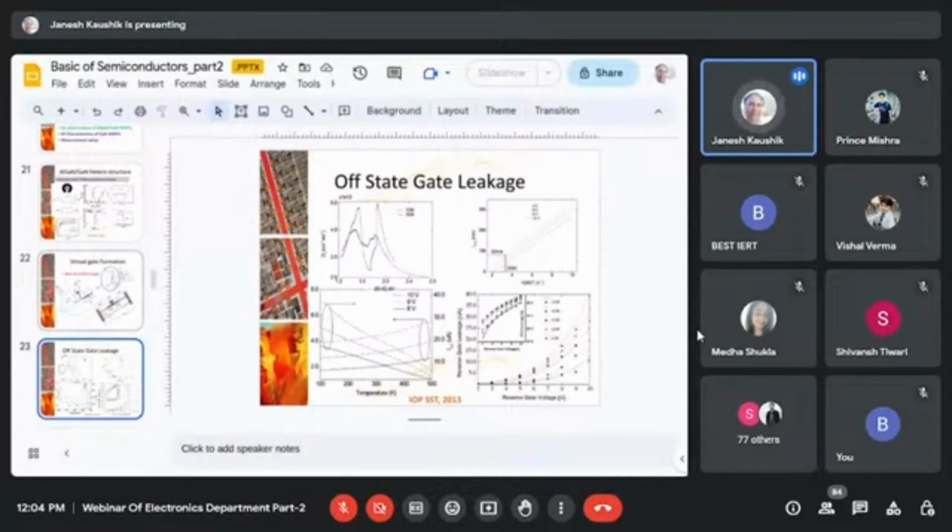The moment we get the D_it, we can integrate to match with the 2DEG available in the channel to calculate where our Fermi level lies. The moment we calculate where our Fermi level is, we can calculate how many carriers are available and how many are participating.